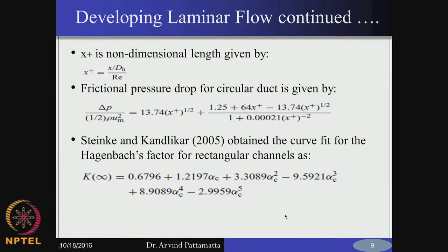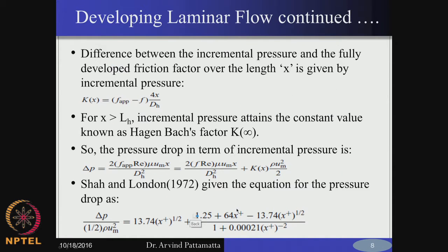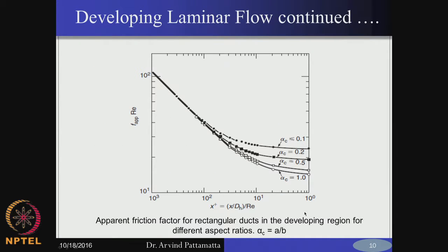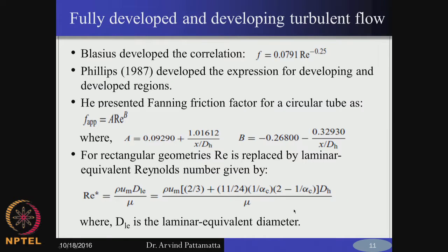Okay. So, you substitute your x as L by d basically if you want to calculate the pressure drop for the entire length. Then that becomes L by d by Re, which becomes a constant value, and therefore, this will give you the overall pressure drop for the entire micro channel. So, these are some of the commonly used methods of estimating the pressure drop for ducts with different cross sectional shapes, and those are for the laminar flow.